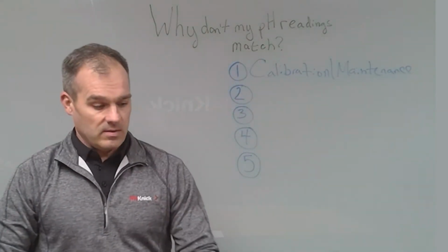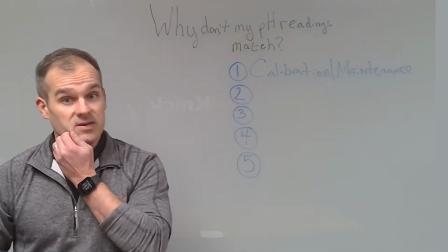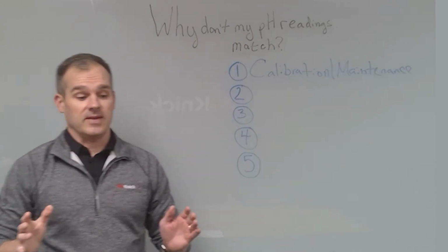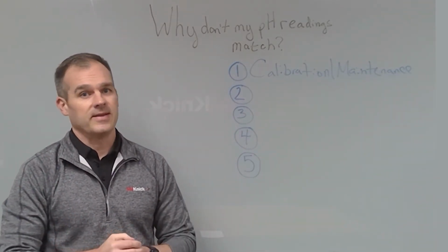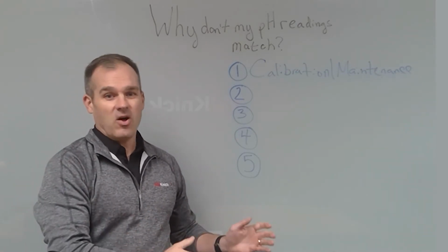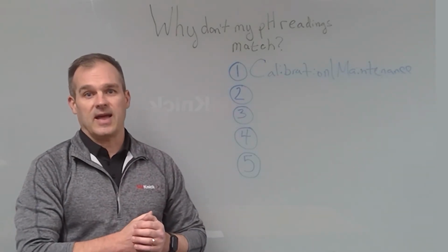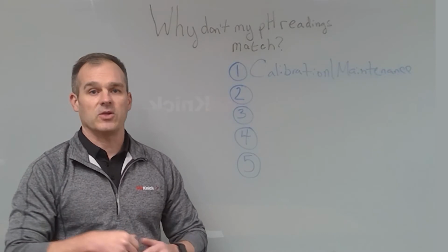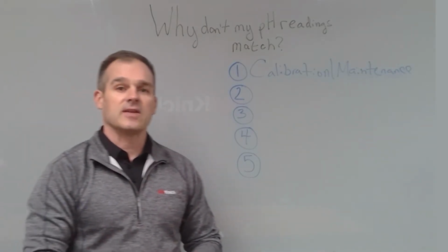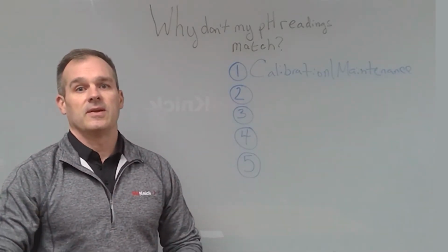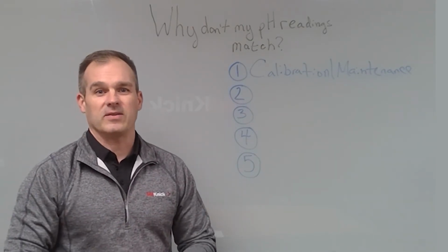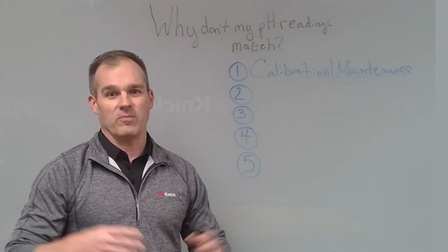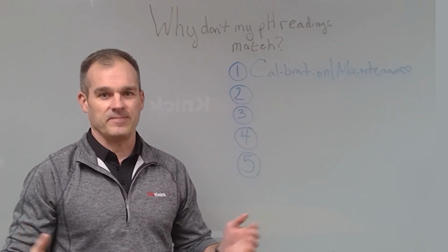Okay, when I'm talking about calibration, it's really the frequency and the quality of the calibration. So let's start with quality. Your measurement itself is only as good as the calibration that was done on the sensor. So make sure you have very clear and concise calibration procedures, that you use fresh buffers, and if you're using an M4 Knick product, we recommend that you use your Portavo with MemoSense offline.